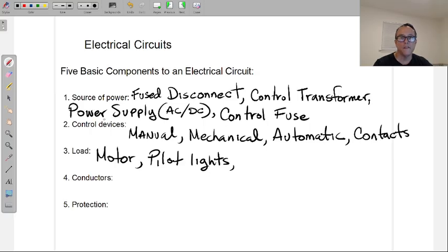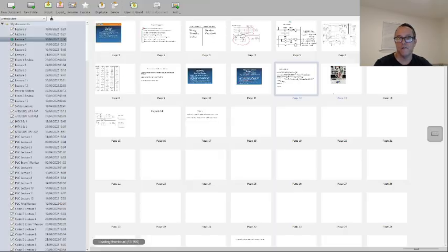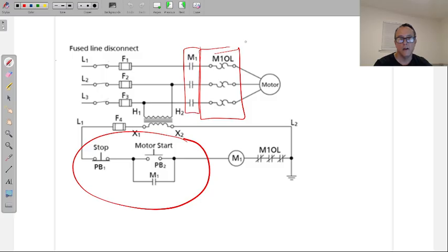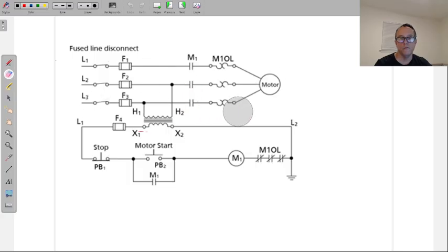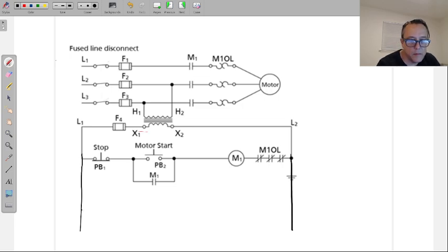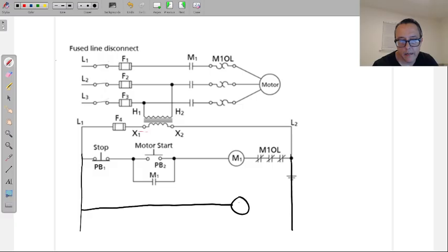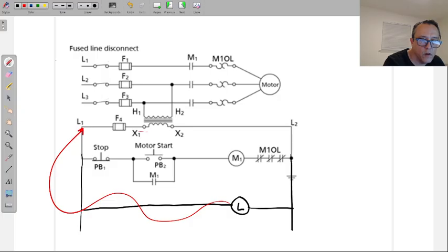By the way, one of the things that I like to do, just to point that out for a second while we're talking pilot lights, I'll use this one since I have space. One of the things I could do to get ahead of a problem is start by checking to see if I have power at all in the control circuit. So I can simply attach a light here to the ladder, to L1. I send a wire from this light all the way over to L1, wherever L1 is. As I said, usually a terminal block with a bunch of L1s.